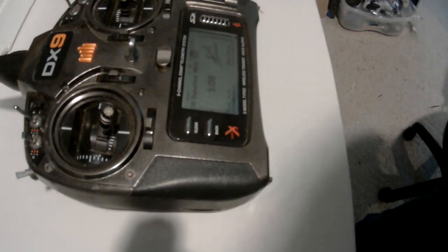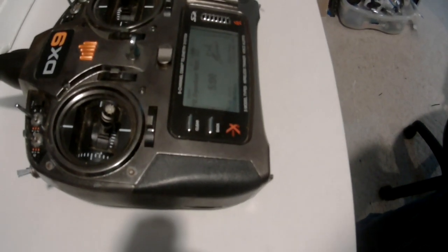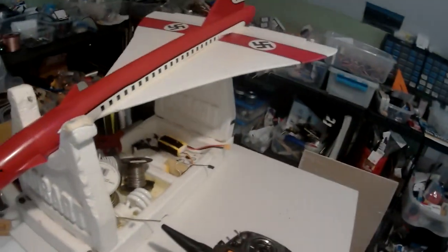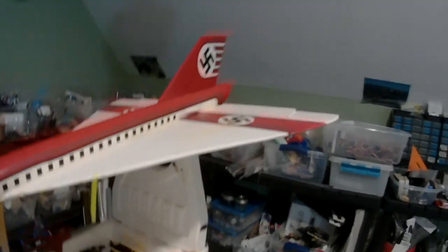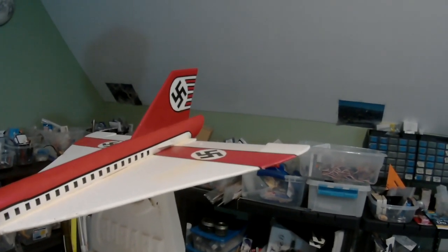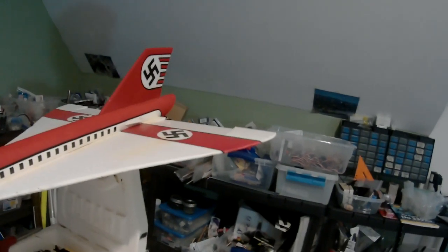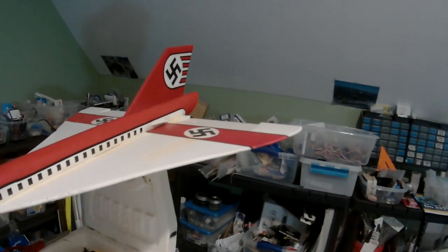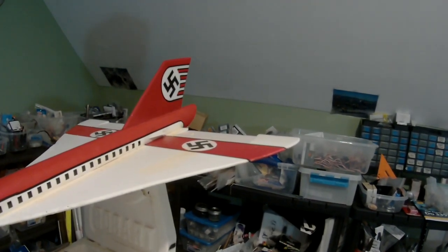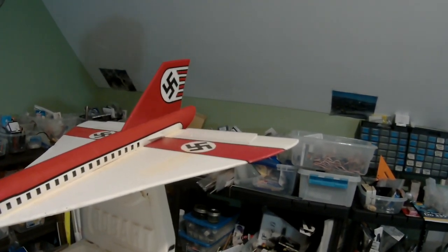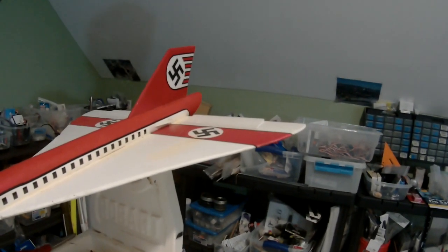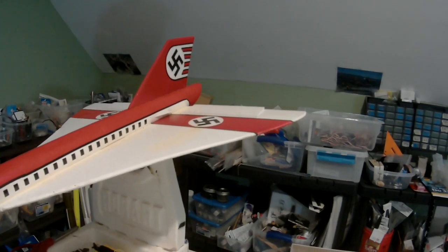Okay, and I have powered up the Man in the High Castle supersonic transport. So we see it here. So just to demonstrate, so I got the Elevons, we're in launch mode, which actually needs a little bit of down elevator. So it would boost to apogee. Then when you hit burnout and apogee and nose over, then you hit the switch and you get a little bit of up elevator. So really simple, and again, that's using the flaps menu.